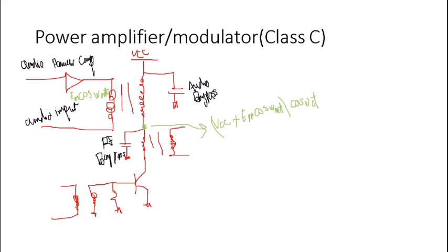Because as we studied before, this is basically how the output of the Class C power amplifier is, given that here we have a signal with a frequency of f_c. By taking that into consideration, we can also assume that the maximum amplitude for our signal that's coming out of the audio amplifier, E_m max right here, is equal to VCC, only given when the modulation index equals 1.